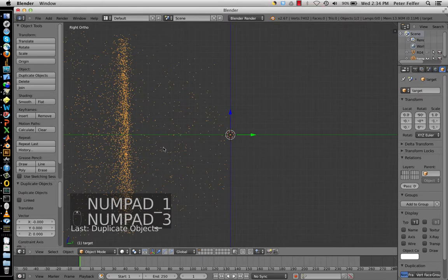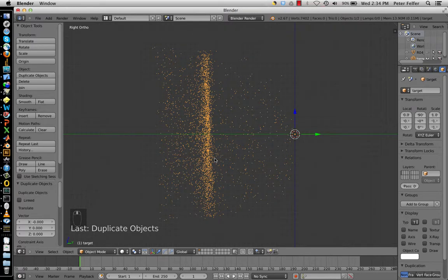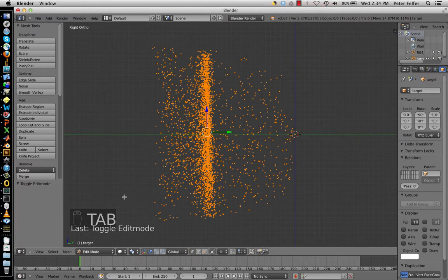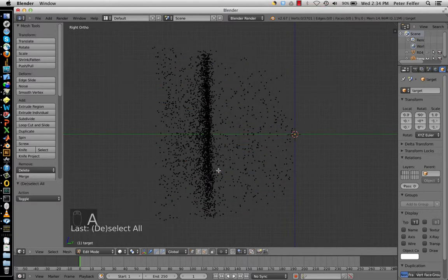Next thing is we only need a certain region. It makes the entire approximation go faster if we remove all the atoms that we don't really need. And to do that, we'll go from object mode, where we're dealing with entire objects, to edit mode, where we're dealing with the data inside the objects. So right now we've got all atoms selected. So let's just deselect all atoms. And here you see circle select. We'll also need to switch into wireframe mode, because otherwise if an atom is behind another atom, it will not select it.